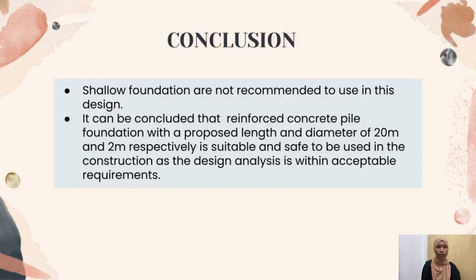For the conclusion, shallow foundation is not recommended for use in this design. It can be concluded that a reinforced concrete pile foundation with a proposed length and diameter of 20 meters and 2 meters respectively is suitable and safe to be used in the construction, as the design analysis is within acceptable requirements.